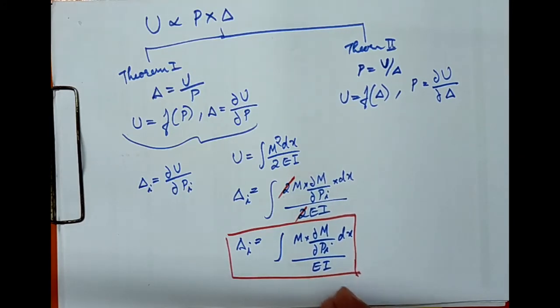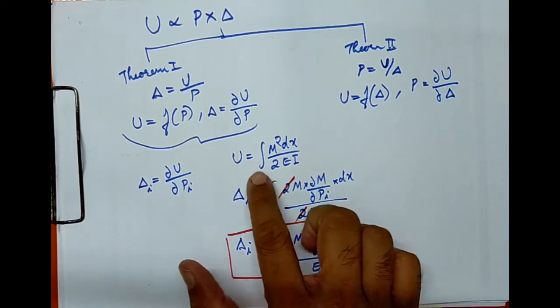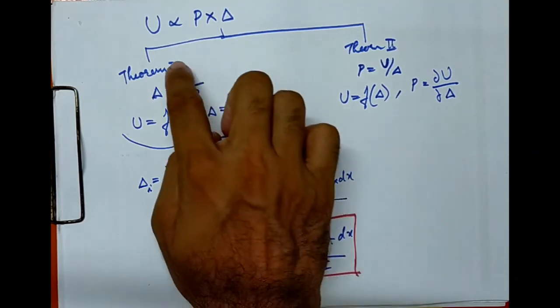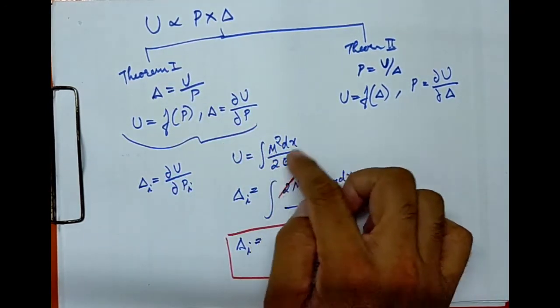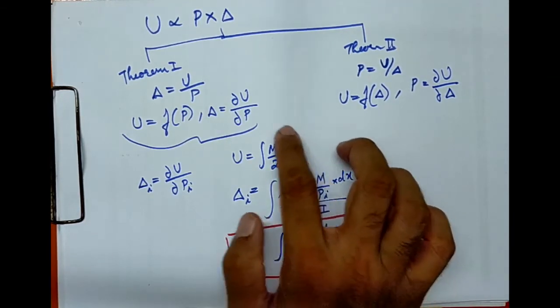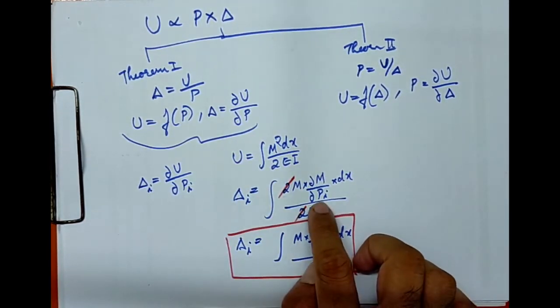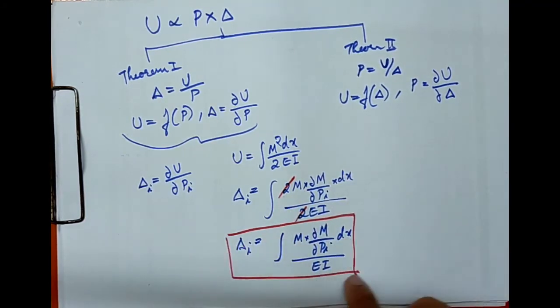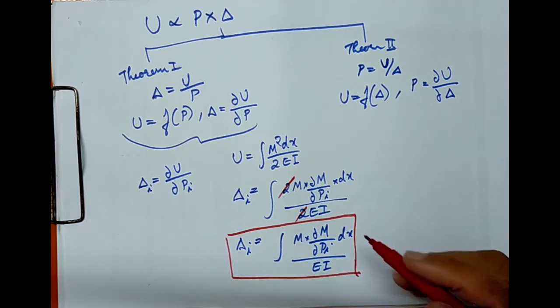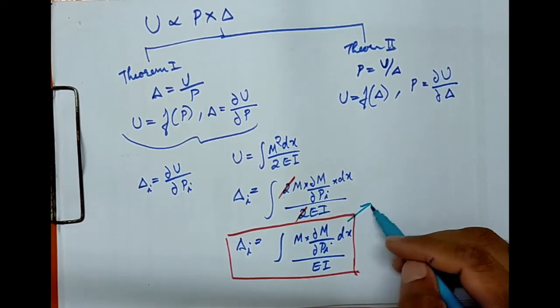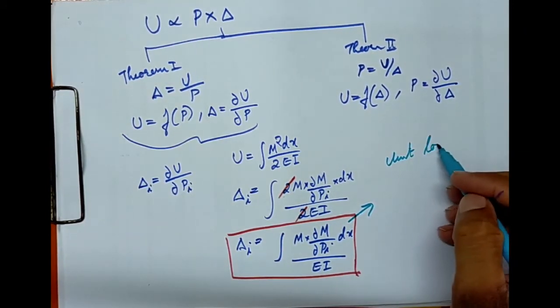Okay, so we have seen the step-by-step way of deriving this equation, because there are a lot of parameters or variables involved in this equation that at the time of the exam you may tend to forget. So if you are not getting the proper equation by heart, you can go for the derivation. You need the expression for strain energy, then you just use Castigliano's first theorem, that is dou U by dou P. When you partially differentiate this strain energy with respect to Pi, you get this expression. This same thing is what got converted to the so-called unit load method.